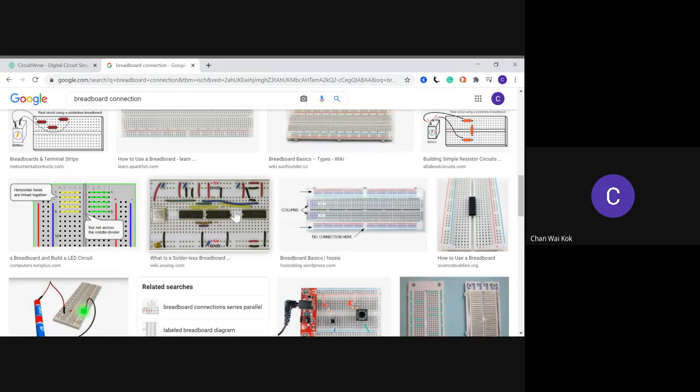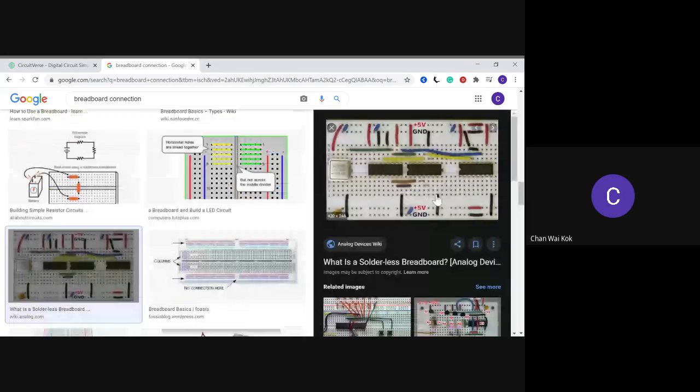You can see this pin 7 is ground, so it's connected to the ground from here to here. Then the VCC is here, connected to pin 14. Red is VCC, black is ground. But this is the color code standard. When you do the lab, you might not follow it. Just see whatever wire you have and use it.